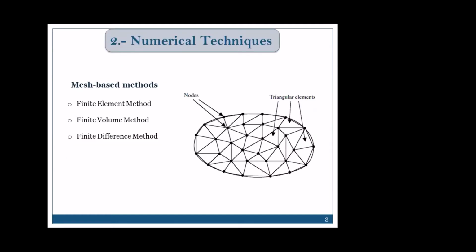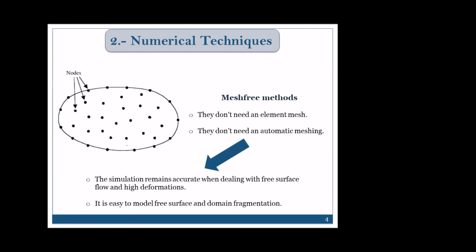There are some traditional numerical techniques, mesh-based, as finite element method, finite volume method, and finite difference method that have been used to analyze these kind of processes. However, recently, the mesh-free formulation is deemed as an alternative to these mesh-based methods because they provide some advantages over mesh-based methods. For example, they use a set of nodes scattered on the problem domain as well as its boundaries to represent the problem domain and its boundaries without requiring any information about the relationships between the nodes, so they do not form an element mesh, which leads to model discontinuities, deformation, and some complex behaviors without the use of remeshing approaches.